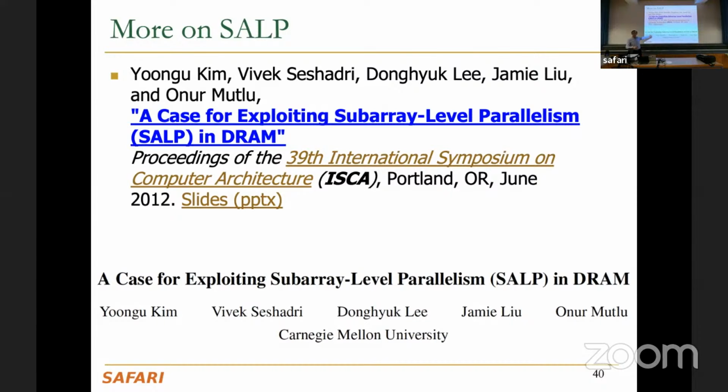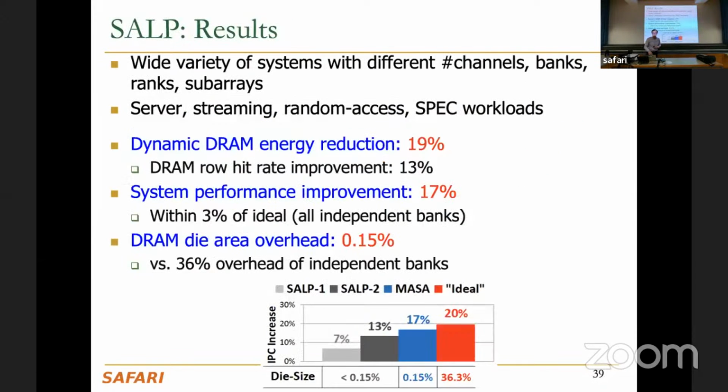which shows that you can actually do part of this in real DRAM chips. So in real DRAM chips, by violating the timing parameters, you can actually activate 2 different subarrays concurrently. So that actually reduces the refresh overheads and RowHammer overheads. This is the HiRA paper that I will probably add over here later on. Does that make sense? So real DRAM chips are actually capable of doing part of this. We always thought it that way, but it required 10 years to actually show it.